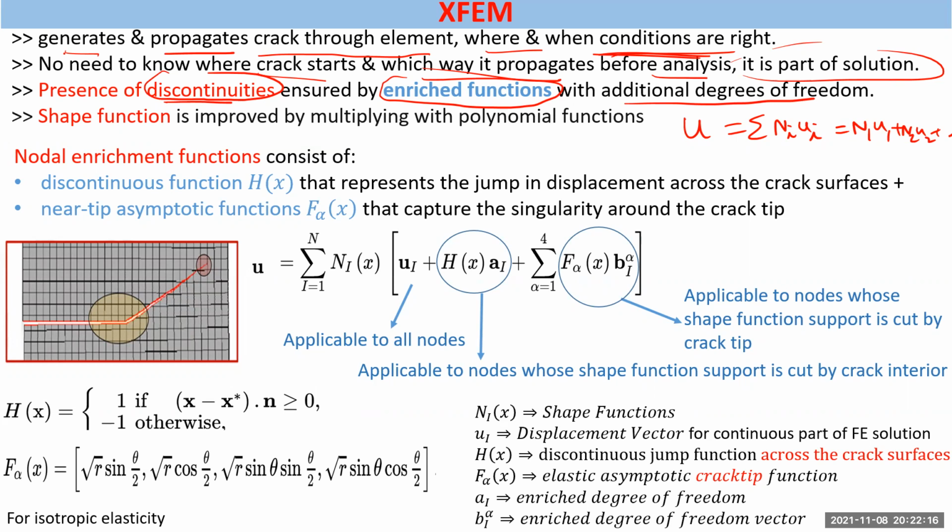We have a shape function for a truss element and a shape function for a beam element, right? The shape functions for a bar or truss element are N1 equals 1 minus x by L and N2 equals x by L, or the other way around. Does anyone remember the shape function for a beam element, or at least the order? In Abaqus also we have assigned the shape functions.